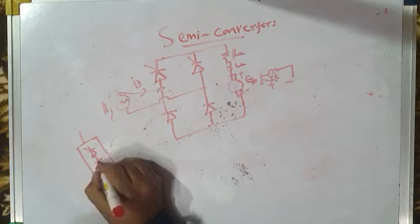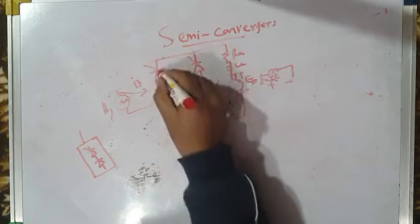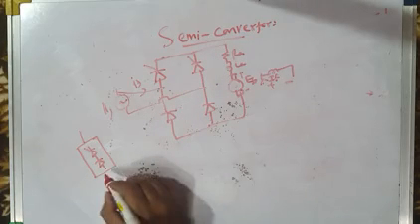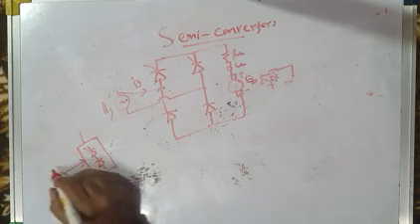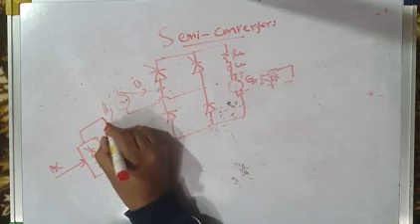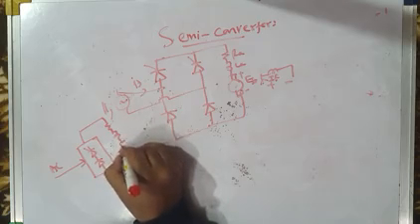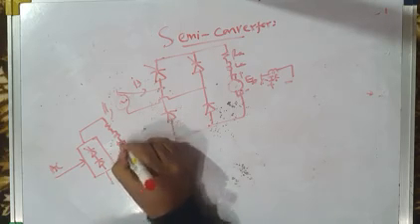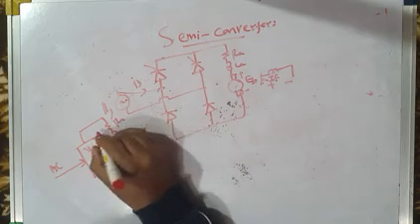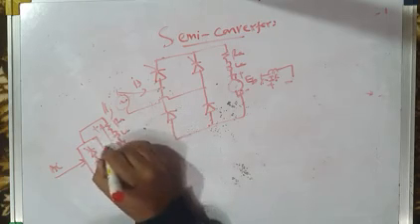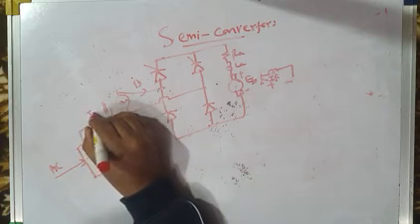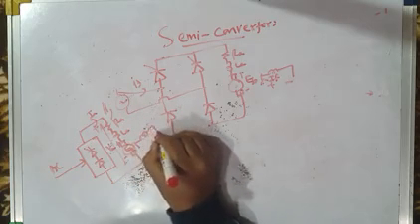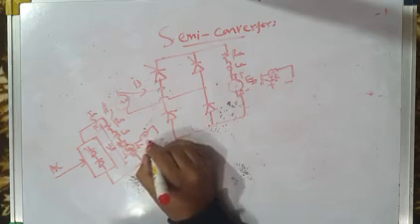Thyristor in series with diode, because in each leg you can see thyristor and diode. It is a single phase supply, so it is AC. This is your load, which is a DC motor. This is back EMF EB, this is RA, this is LA, this is average output voltage or armature voltage VA, this is current IA, and this is the field current IF.